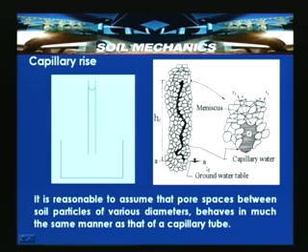In this slide, AA is the level at which the groundwater table exists, that is the free surface where the pressure is zero, and this is the path taken by the capillary rise. HC is the height to which it could rise, depending upon the pore space and the cleanliness of the inner surface of the mineral grains, or the grain wall cleanliness.